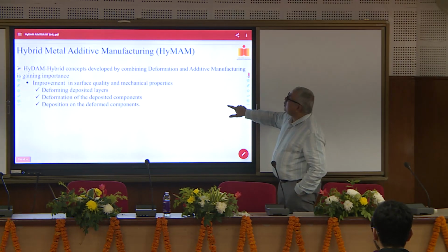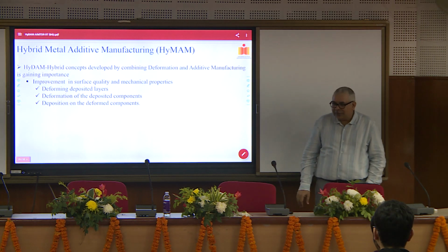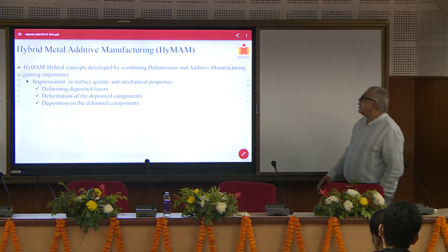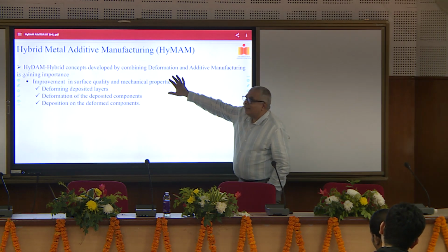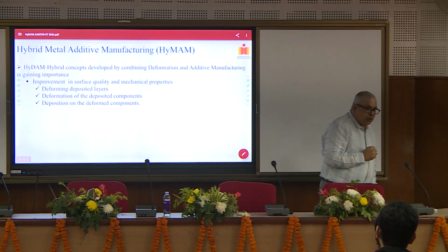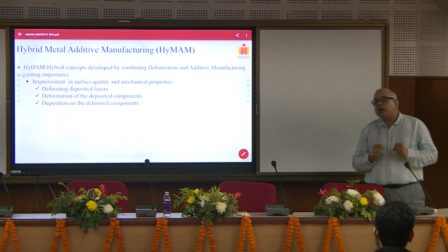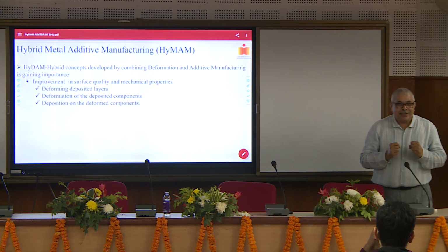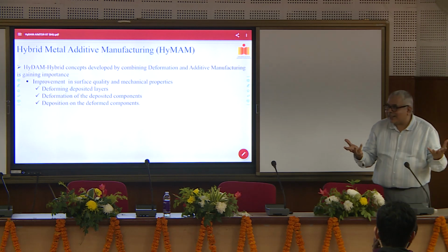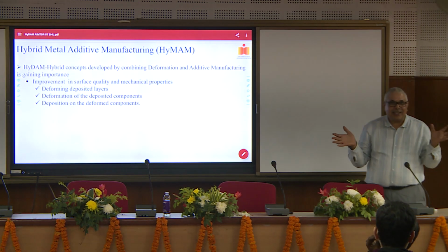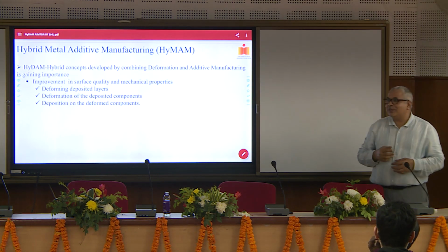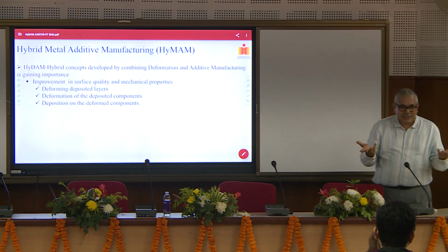Now I'm coming to HIDDEN, which is a word we coined. It is a hybrid concept developed by combining deformation and additive. Why deformation? We all know that when you perform the operation under compressive stresses, the mechanical properties are much better. It's a very well known thing. That is why you sandblast and shot peen the additive manufacturing component, to change the residual stresses even today.